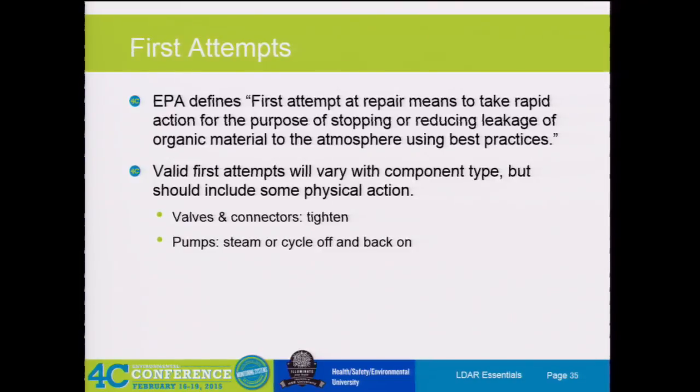So you have a follow-up sniffing after you found that leak, right? But it satisfies that you tried your 5-day requirement right there. Now you automatically have 15 days to figure out how you're going to fix it. With that argument, though, you could say, well, it's not leaking in the first place. If it's only coming from that, it's not leaking any longer. It did at one time, you're saying, the residual from the outside.